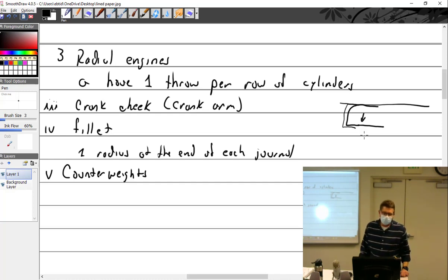And you have to measure very carefully. One of the engine manufacturers, you can change out the bushings in the counterweight. The other one, you can't. They're machined. You're put in and then machined. I hated changing the bushings because they were really pressed in hard, and I was worried about breaking something, but I never did. Yay.